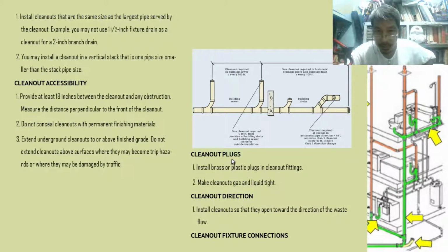Clean out plugs. That is the cover of the clean out. Install brass or plastic plugs in clean out fittings. Number 2, make clean outs gas and liquid tight. So this must be tight, not allowed to leak bad smelling gases. That's why we need to make that plug tight, liquid tight and gas tight.